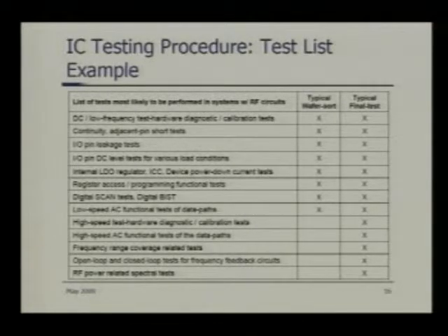Now, if there is any leakage within the RF output buffer, what could happen? It runs well up to say 1.3 gigahertz, and the peak-to-peak swing of the waveform gradually degrades as you move the frequency up, because there is a leakage current path which is stealing the current away from the RF output buffer.